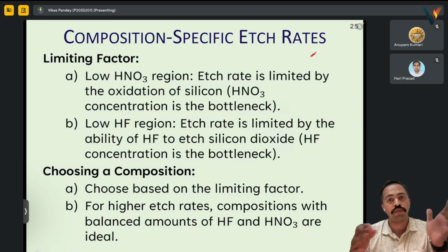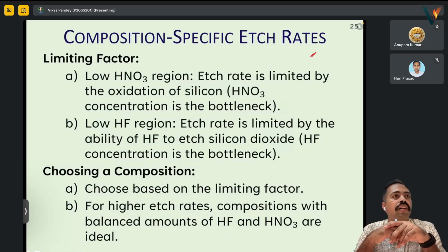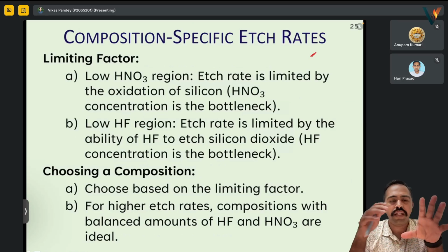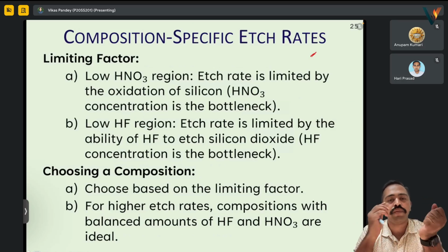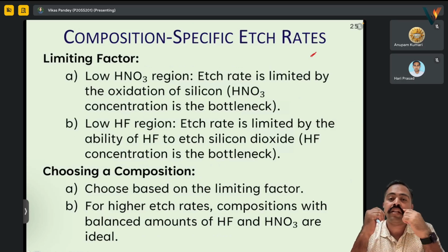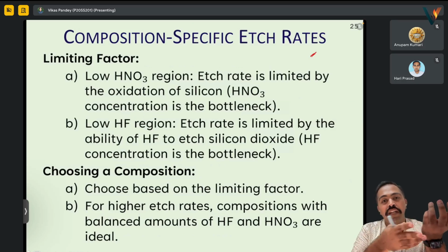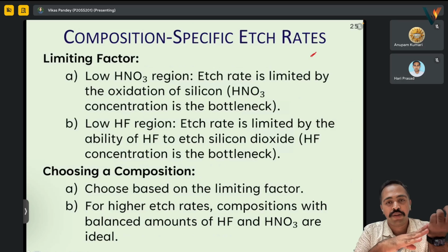Silicon etching is one big part. Metal etchants, there is one list I have not actually put, that you can find, mostly there are chemicals. For metal etching, it is not that complex because metals are not crystals, right? When we are dealing with silicon, it is very complex because we will see later that with the orientation of silicon the etching will change a lot.